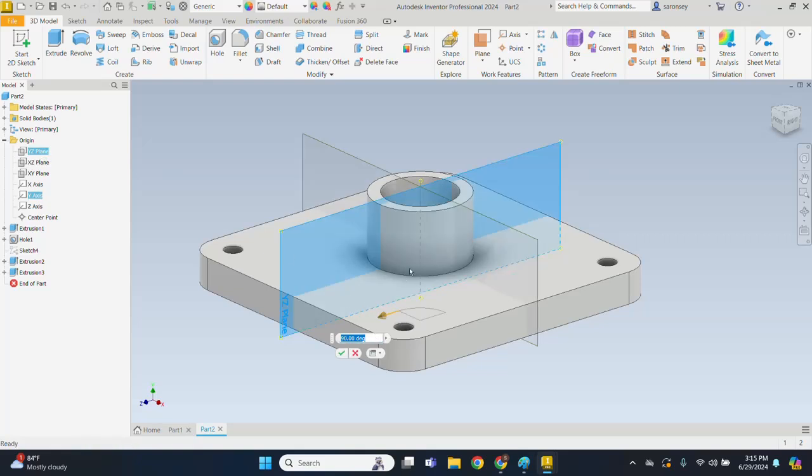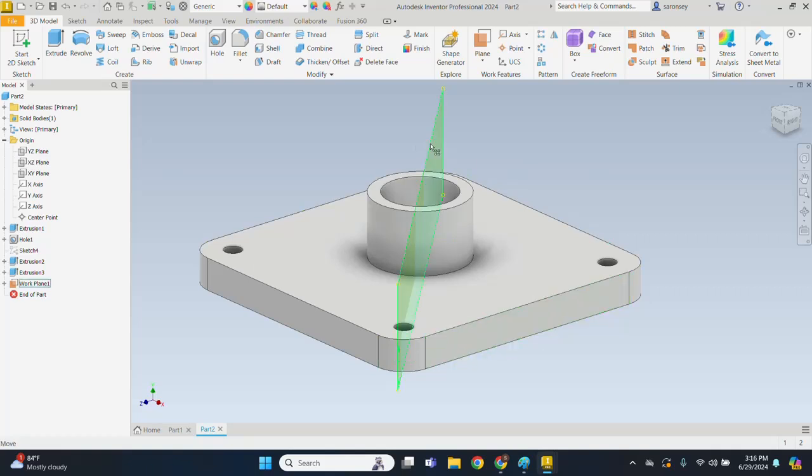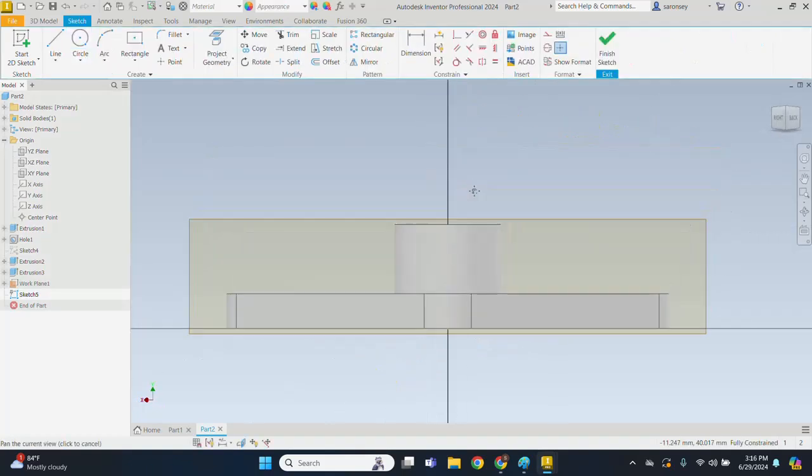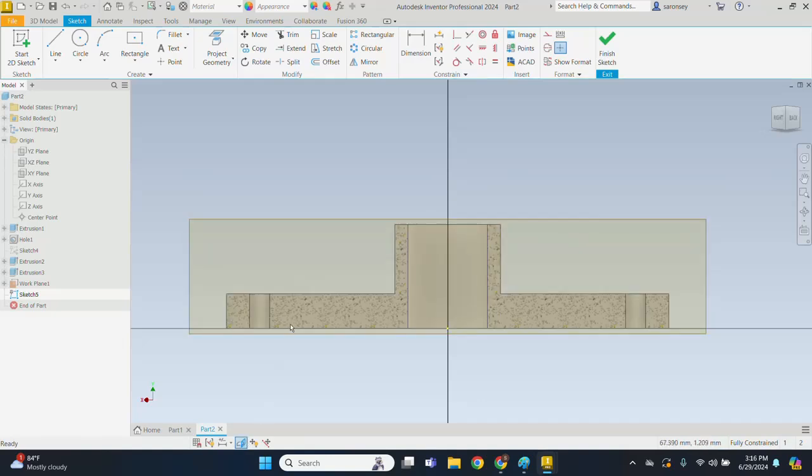Here we want to place the rib at 90 degrees, at 45 degrees, sorry. And so let's change the 90 degrees to 45. And then we can accept that. Let's click on this plane and create our rib. We can choose the sectional view here too.